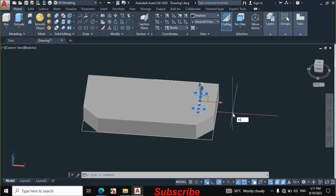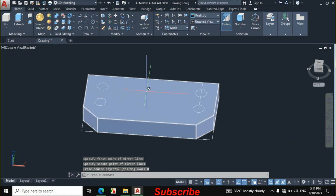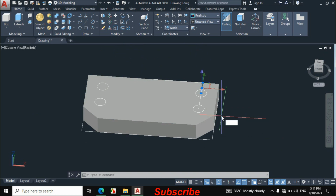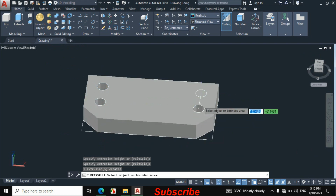Then press MI from the keyboard for mirror, and mirror these two circles from the midpoint, and click on this end point, click on no. So these two circles are mirrored. Then erase this line. Click on this line and select it, click on erase, or press E from the keyboard, enter. So the line will be erased. Now click on press pull, and press pull this circle downward, the same for these two circles.